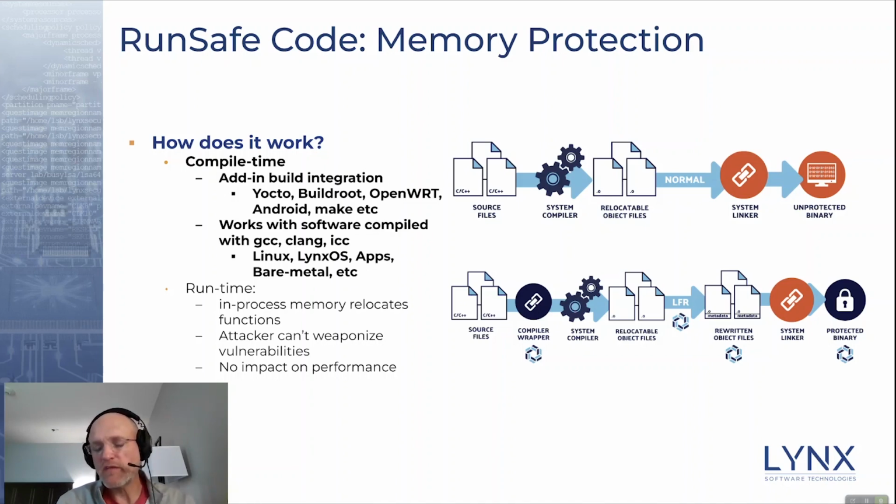The way it works is instead of compilation proceeding directly from the compiler to the system linker, we pause compilation after it's gone through the precompiler and once the .o files have been created. We analyze those .o files to highlight function sizes, locations, and cross-references, and that content is then added on to the end of the .o file in a new section called the text.rp.